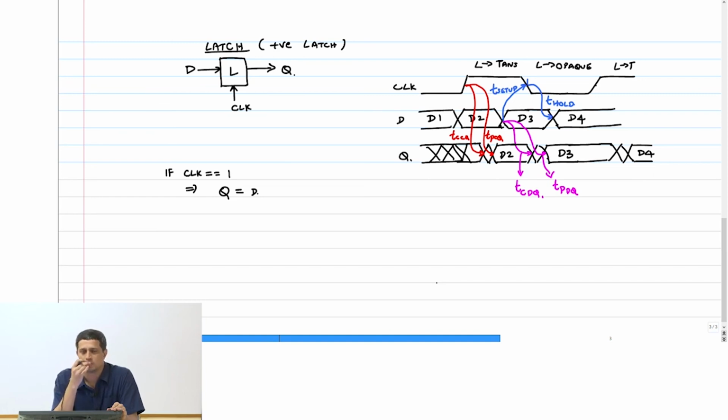You hold the previous value, or you just leave it. Actually, if you're trying to write this in very long form, you can just leave this, right? If I were to implement this in terms of logic gates, where I have if clock equal to 0, then hold Q. Let's say, what is the best logic gate I can use to implement this?